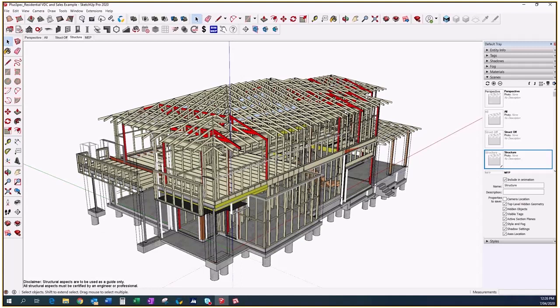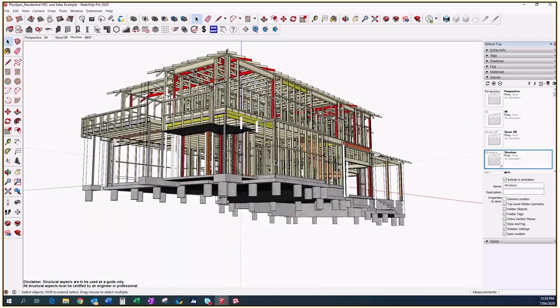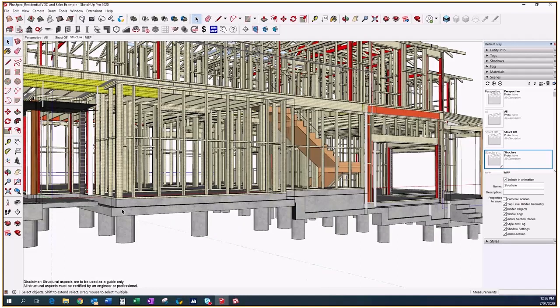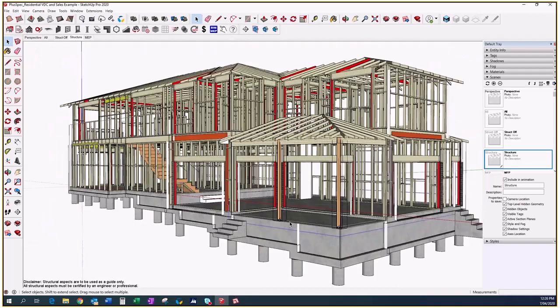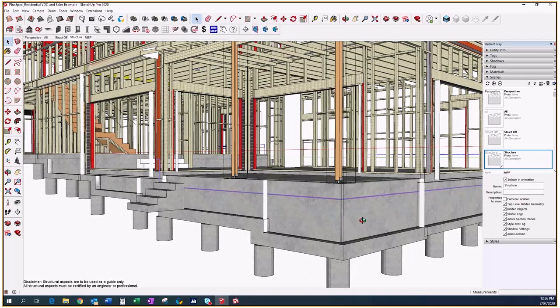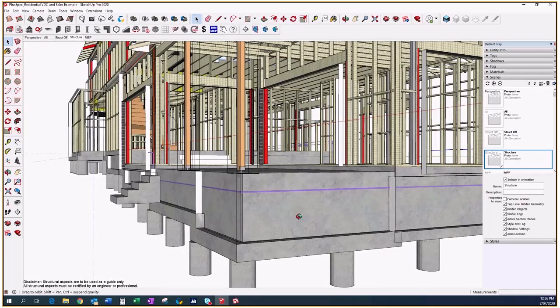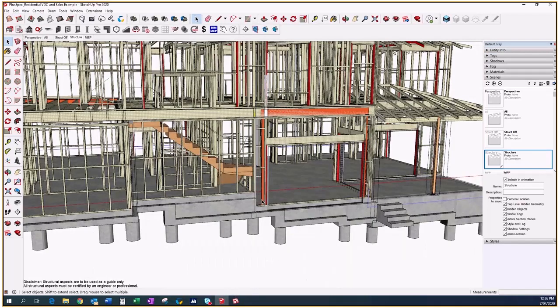This resolves that. And this is still a fairly simple model, but you can see that it's got quite complex footings. It's got all of the stairs, the slab, the way the MEP is reacting, drop edge beams. Drop edge beams are one of the number one mistakes that a lot of people make, because normal software, when it's not virtual design and construction, it's too simplified. It's allowing you to make those errors because it's not forcing you to think, what are you doing structurally?